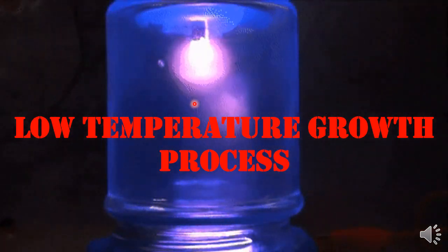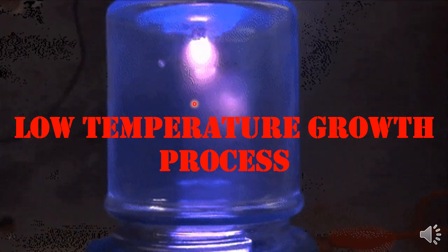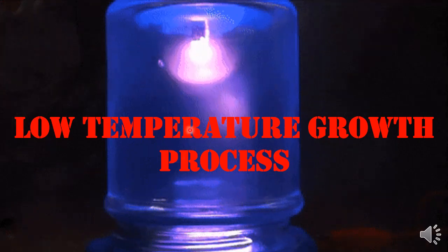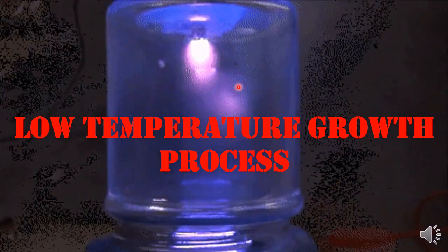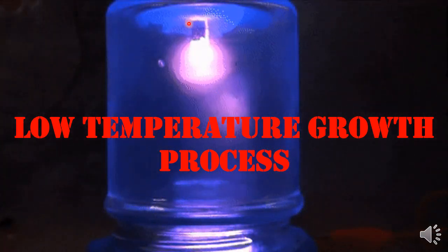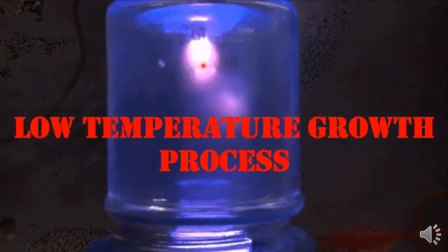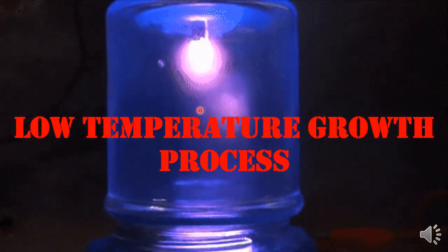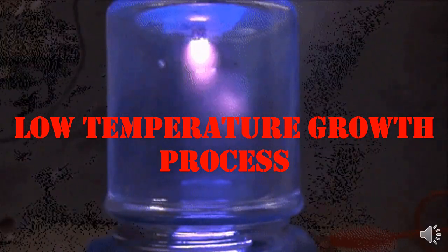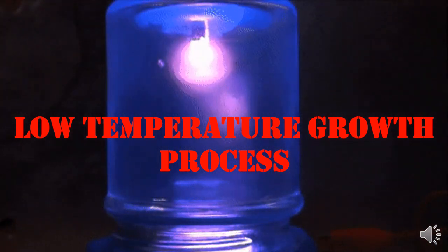Another key advantage of this technique is that we can deposit ultra thin film. The film is very thin, in a few nanometers. Since the film is usually deposited on the substrate, the temperature inside the reaction chamber is less, and the temperature of the substrate is also less, so the incorporation of impurity from the substrate becomes very low. So this technique gives us an opportunity to deposit ultra thin film, which is not possible with the other available chemical vapor or physical vapor deposition techniques.